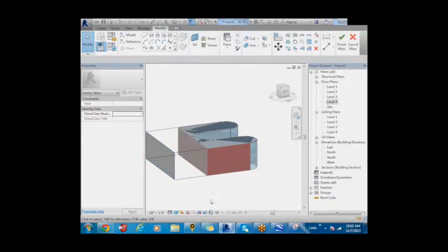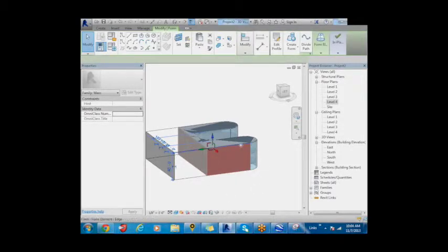So we do this. Initially, Revit is not smart enough to understand that it has to resize the walls and the floors and the roof along with the conceptual mass. So what we do is, after resizing the conceptual mass, we then click on a particular element. We would want the wall to extend till the end. So we click on the wall.